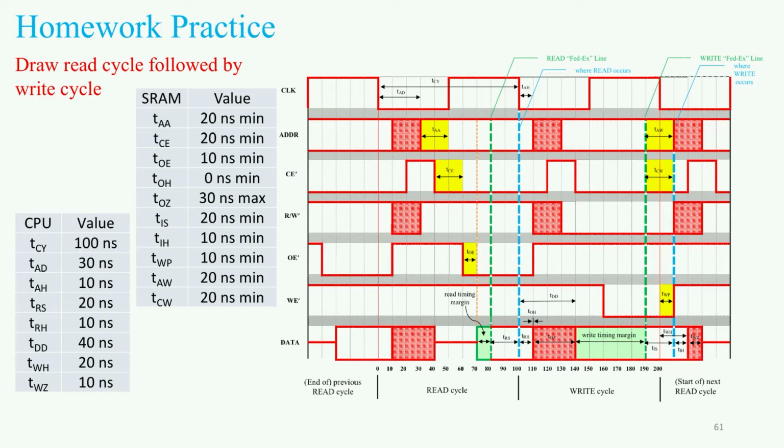Now let's go down and take a look at what happens to the chip enable line. Remember, if we look back to our original diagram, which you should always have an idea of in your head or have in front of you when you're doing these things. On your exam, you'll be given the lecture summary notes, so you'll have those pictures so you can visualize what's happening. We can remember that the chip enable bit is dependent completely on the address bus. The address was constant and valid for this entire phase, so the chip enable bit was constant and valid for this entire phase.